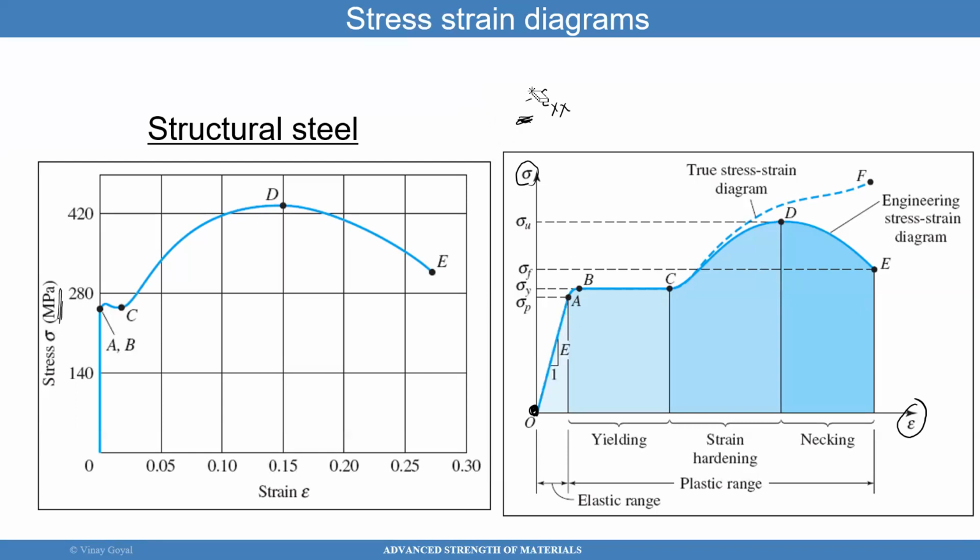That's the idea there. The problem is it's hard to achieve for a lot of components because, for example, engine components get really hot, and so you get some amount of yielding. And the yielding is occurring in this zone, for example, the zone between B and C. And I'm blowing up B and C. So I'm blowing up this region here so you can better see what's going on on the right-hand side. So I'm blowing up that curve. I'm zooming in between points B and C there.